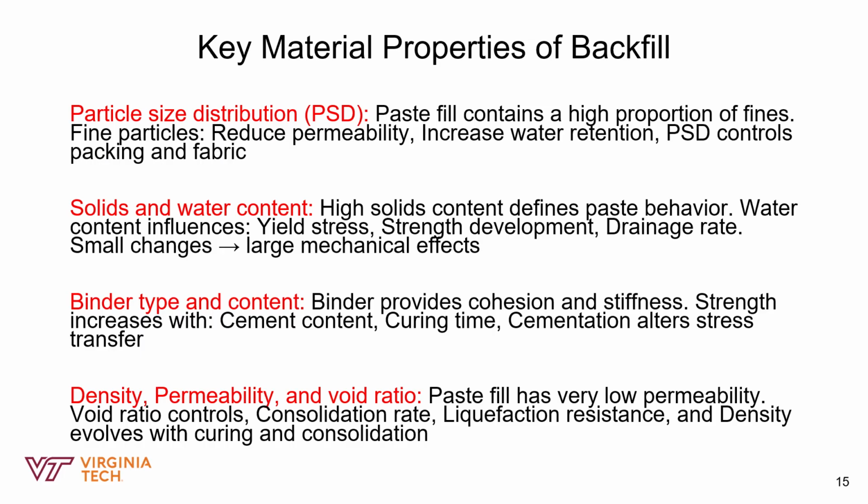The third one is the binder type and content. The binder is basically more like our glue. When we use cement, it provides cohesion and stiffness, and as you would expect, more cement means higher strength, but it also changes how the stress is transferred to the rock walls.